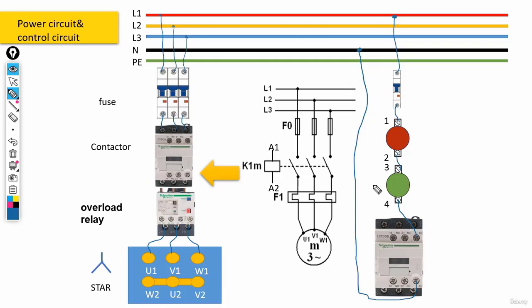Now, if we go ahead and start pushing this start push button down, the contactor would start working. More precisely, the contacts here would start working, and as a result of all of this, the motor would obviously be turned on. Okay, and when we stop pushing this button down, obviously, again, the contactor would stop working, it would be cut off, and the motor would be turned off.